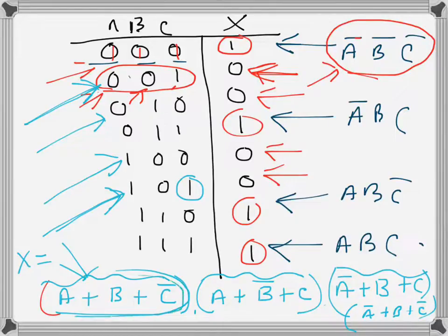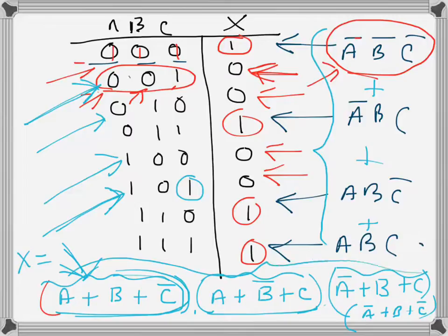So these are the sums here and the product there, so it is just the opposite, just another representation of the truth table, from the same truth table. So this product of sums expression and the sum of products expression, the one I did in the previous video, when these four are added, are equivalent representations of the same truth table. So this is the output in terms of sum of products, while this one is the output in terms of product of sums.